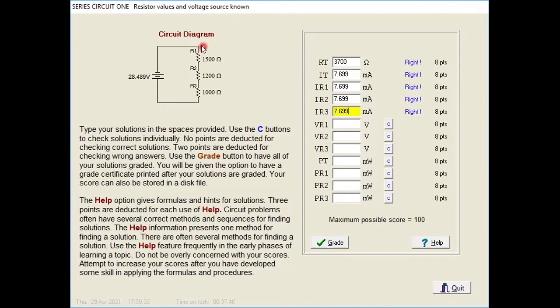Okay, so if I was to take a voltmeter and measure across R1, I would see some voltage drop. If I take another voltmeter and go across R2, I'm going to see voltage drop, and the same thing for R3. Now, each one of these resistors drops some voltage. Which one would drop the most? Well, the highest resistance. That's the one that opposes current flow the most. So this will drop the most voltage. Which one would drop the least? Well, using that method, we're going to look at this and say the smallest resistance would drop the least. These are very important concepts to understand.